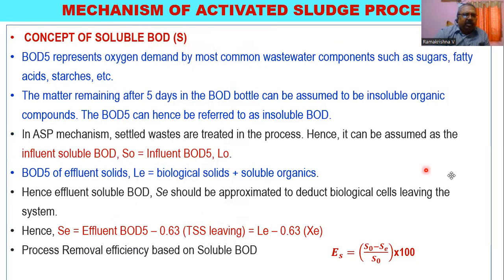Now let us look at another term which is also used in the treatment systems of ASP: soluble BOD. There is a 5-day BOD and then again soluble BOD. Is there any difference between soluble BOD and BOD5? We'll look at it. BOD5 represents oxygen demand by most common wastewater components such as sugars, fatty acids, and starches.